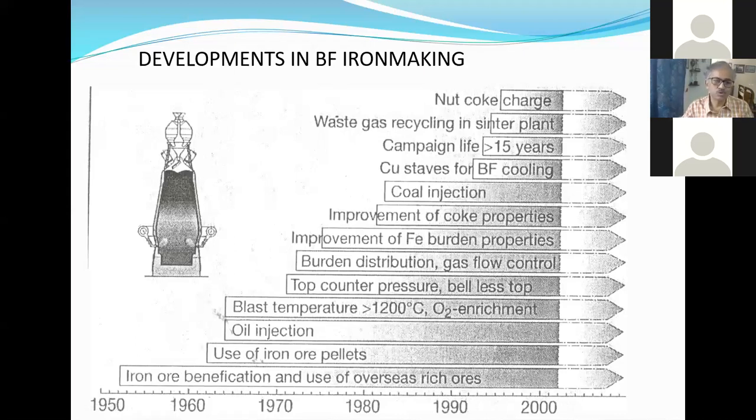Obviously, you can increase the total iron. Then iron ore pellets use came because pellets give a very nice permeability. If you consider the permeability, pellets give very good permeability in the dry zone, because the lumpy ores, because they are very strong.